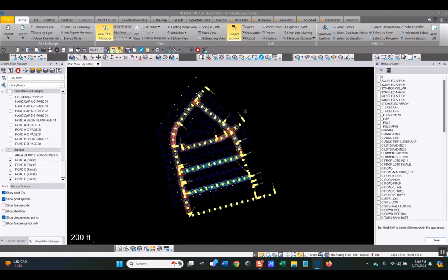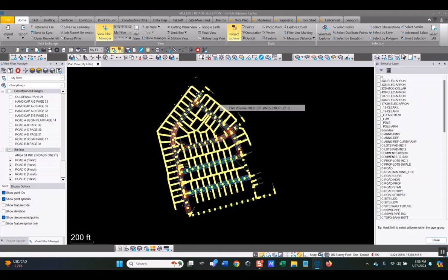So what we're going to do is, given that capability, I can pick that entity, I can pick another entity, I can pick as many different layers just by simply picking a particular entity that I visually see, and it grabs and selects that data. So that's a marvelous command. I use it probably, I don't know, guessing 40% of the time as I'm working in TBC.